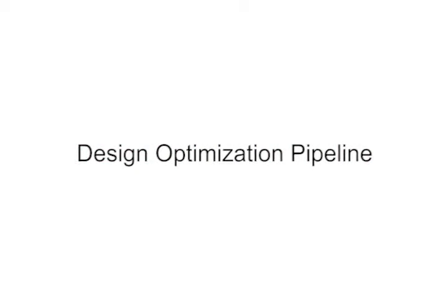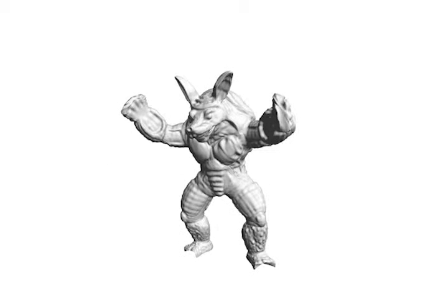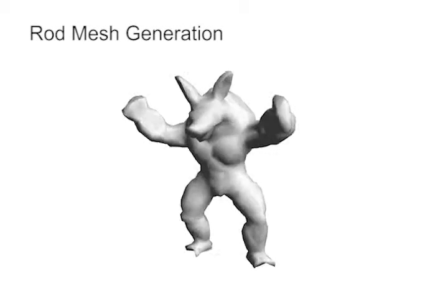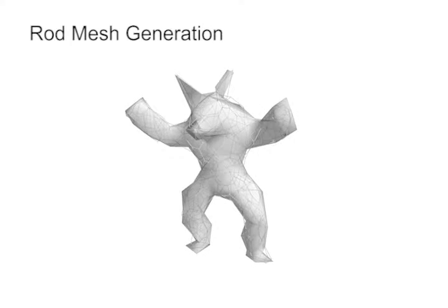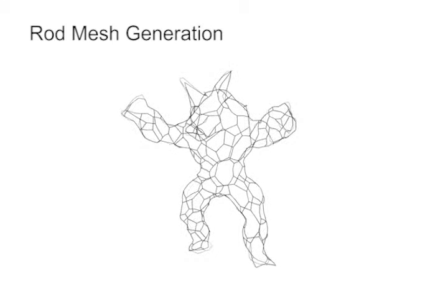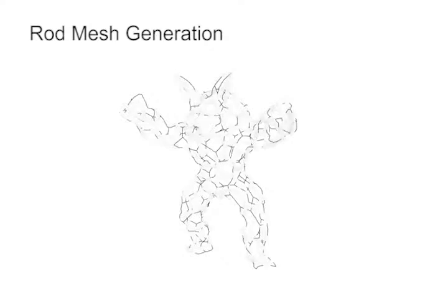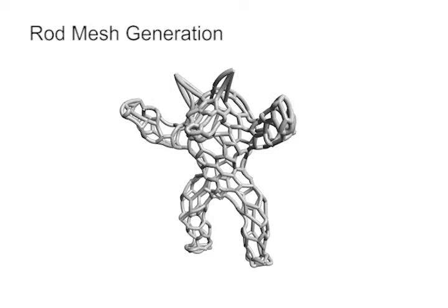We now present our pipeline for the design of active 3D printed rod structures with multi-material distribution. Here we use the Stanford armadillo to showcase our approach. First, we convert the triangle surface mesh into a Cosserat rod structure. In this example, we apply mesh simplification and project the dual lines back onto the original mesh. The dual lines are solidified into Cosserat rods.